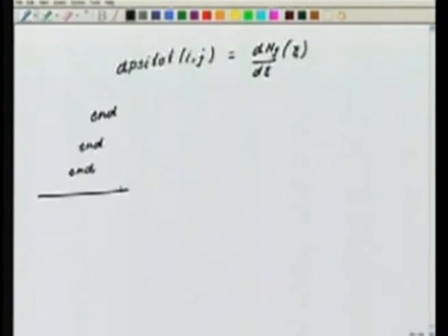Okay. So, this is a routine which will take the integration points and the order of the shape functions that we want. It will go to my shape function routine, return the values of the shape functions and the derivatives of the shape functions with respect to the master coordinate at each of these integration points, and store them in arrays to which we have given some names. The first array is the array of the shape functions, PSI dot, and the second one is the array of the derivatives, DPSI dot. Once we have loaded these, then in all elements when we do the integration, we do not need to call the shape function routine over and over again. We can simply use these two arrays that we have created, and these are not big, they are very small in size. Okay. We can simply use them over and over again in each of the element calculations.